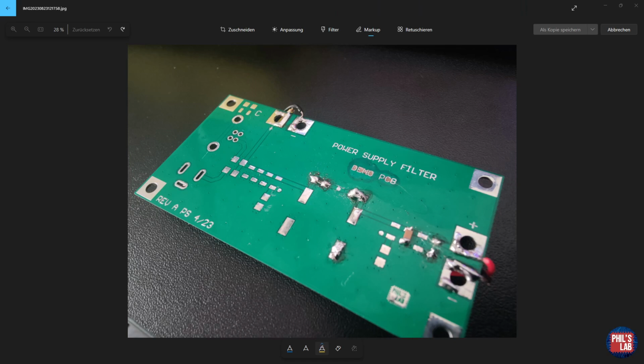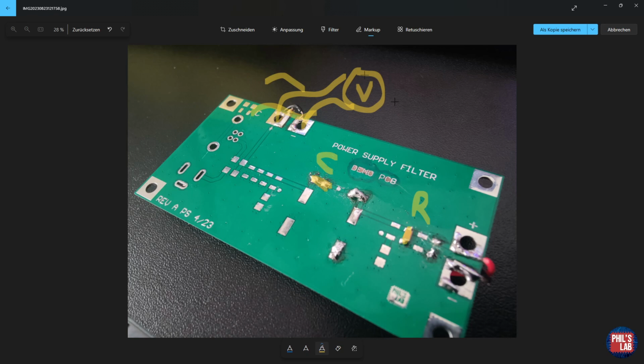Now let's examine this RC high-pass filter in the time domain in the real world. To do this, we'll use this demo PCB. I've soldered in a capacitor, which is 100 nanofarads in series, and at the output a parallel resistor, R, which is 22 kiloohms. And we'll need that to form our RC time constant. I feed in an input signal from a function generator and also measure the input signal. At the output, I also attach an oscilloscope probe to measure the RC high-pass filter response.